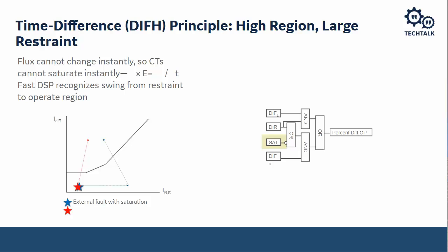It actually makes you less secure. So when setting these, have caution in that respect. That sort of covers the differential aspect on how the low impedance differential can be used to securely protect your bus and offer you high-speed protection for arc flash.